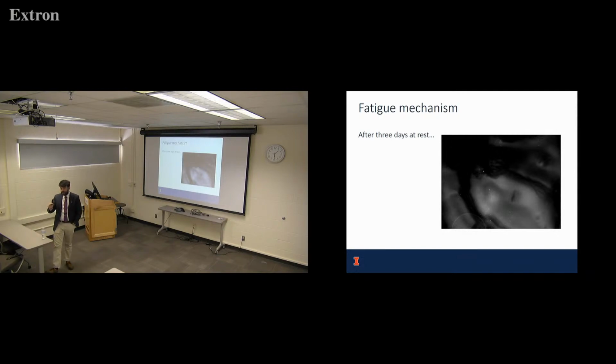I think it can be up to 80, but the reason they say up to 80 is that they took a couple of different scales, applied a macro stress, and then measured the worst-case scenario from all scales. For example, at the pavement scale, maybe in asphalt you can have a stress 5 times as much in a certain part of the mix as you do in the bulk from the tire. Then in the mixture phase, you could have a stress, what's 80 divided by 5? 16. Thank you. So you could have 16 times the stress in the binder versus the mixture. If you compound those two, 5 times 16, you get 80 times worse stress in the binder than overall in the pavement structure. Does that make sense? Yeah, it makes sense.